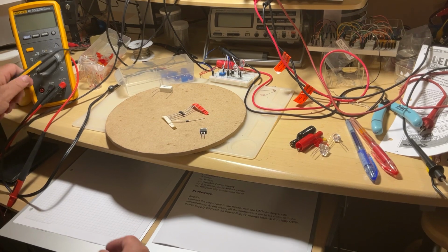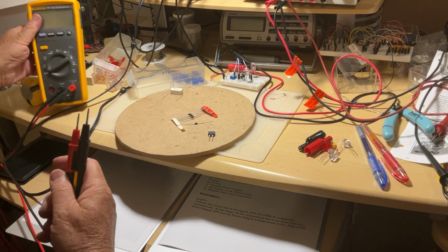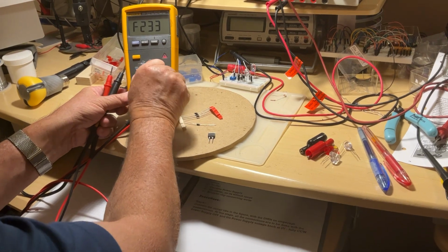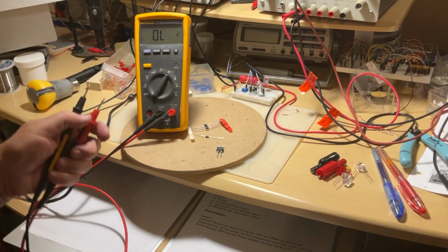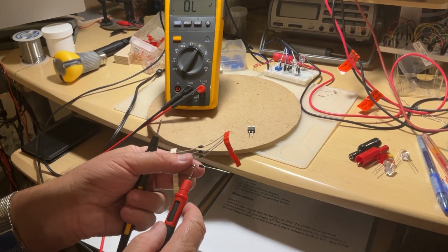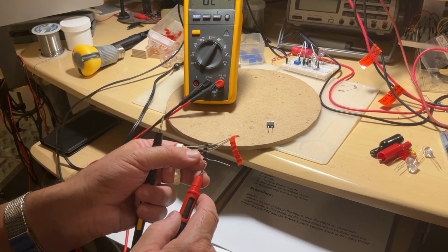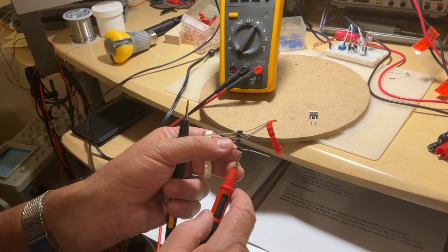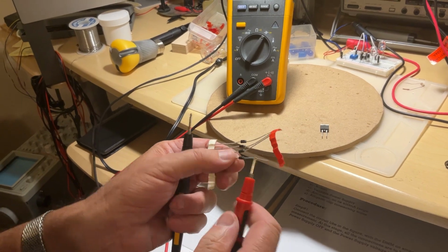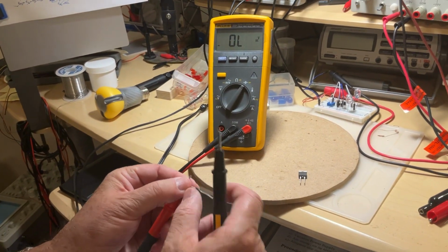Let's start with the measurement. We put a meter on diode, we pick up one of them, and we measure. The diode has two terminals, as you know, anode and cathode. On the rectifiers, they always mark the cathode. If the body is black, they're going to have a kind of lighter ring, like this one is a kind of silver color.